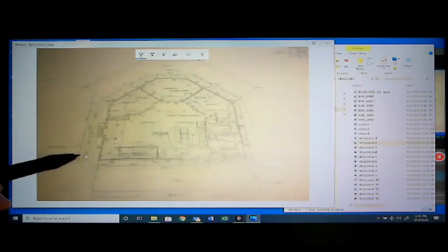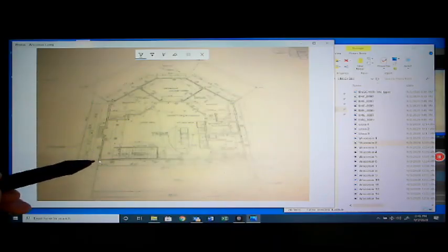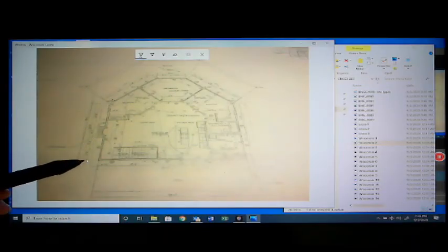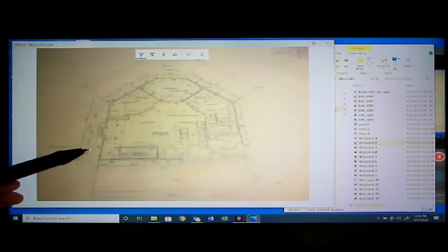Nothing that's not real. Extension lines aren't real. They're just for the purpose of getting to the dimensions. It's not part of the body, it's not connected to the body. So anyway, you come out, and basically we came about a quarter inch past the nearest obstruction, and then you can see in this case, we have measuring from here to, this would be to the center of that window.